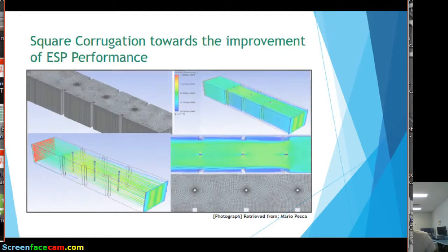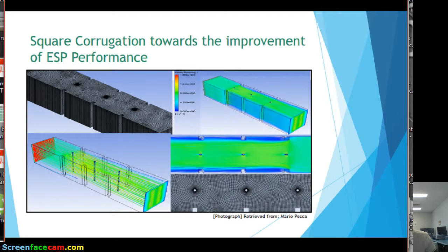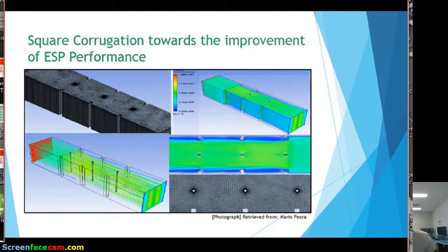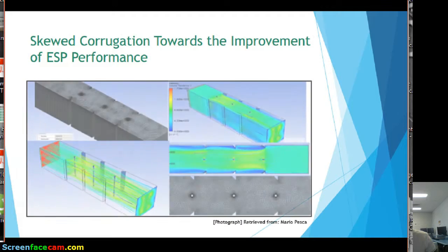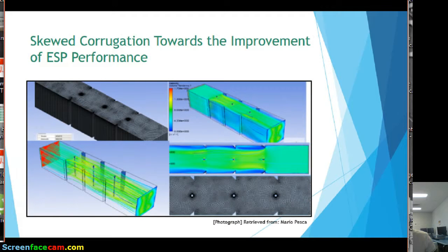On this model, we use square baffles to represent the corrugation on the collecting electrodes, increasing areas of low velocities for individual channels, which is then multiplied by the number of channels in the precipitators. Then a change of geometry was imminent, since the square baffles also introduced parasite drag. Now, based on Bernoulli's theorem, the introduction of convergent and divergent baffles was considered as a solution due to the angle of attack being able to affect the behavior of the flow.